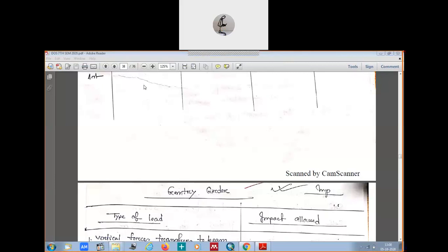Now we will talk about the maximum bending moment. In the first class we talked about where we have the maximum load and how to calculate it. When we know where it is, we can find out the reactions. Also, we know the position of the maximum shear force on the gantry girder. Now, where will your maximum bending moment be, and once you know where it is, you can calculate the bending moment after knowing the reactions.